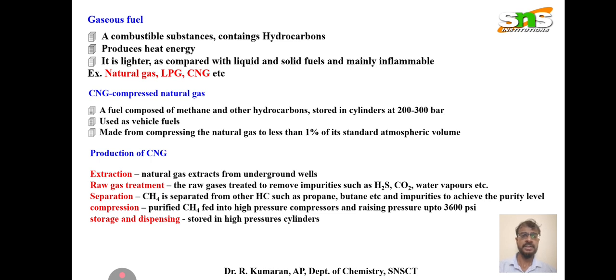CNG, the acronym, is compressed natural gas. It is a fuel composed of methane and other hydrocarbons stored in cylinders at 200 to 300 bar of pressure, which is called the compressed form of natural gas. It is used as a vehicle fuel. It is made by compressing natural gas to less than 1% of the standard atmospheric volume.